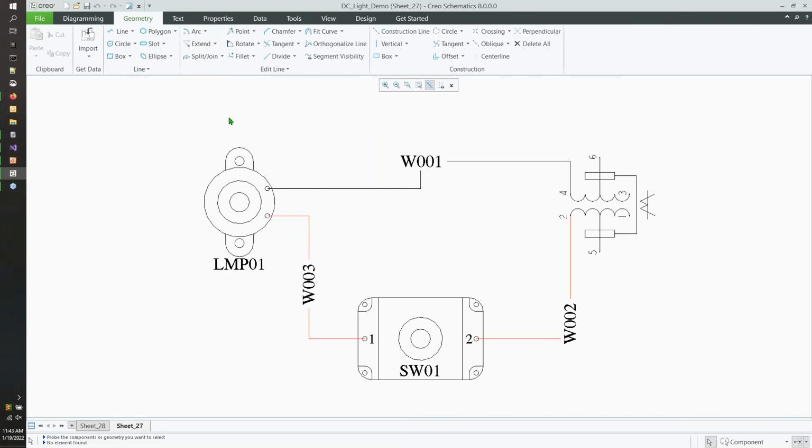Of course, we have a geometry tab. This is the stuff of 2D stick people creation, so that we can go ahead and create these types of artifacts or shapes, if you will. It's referred to as an artifact here inside of our schematic designs. So we use this geometry tab to create these things. To be clear, yes, it is possible to bring these types of 2D shapes and structures in from AutoCAD DXFs and DWGs and those more formal prehistoric structures, if you will. They can definitely be used to bring them into Creo Schematics and automate some applications of custom things that you may have going on in some legacy product or something to that effect.